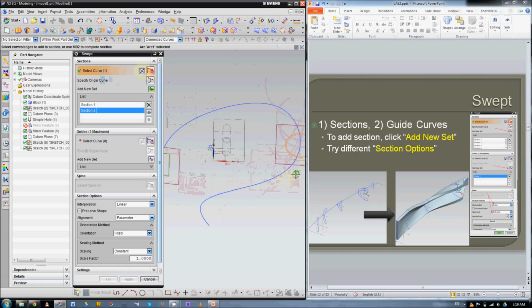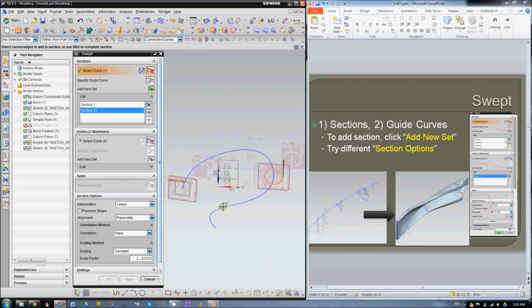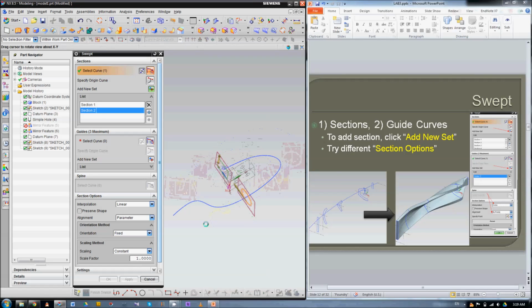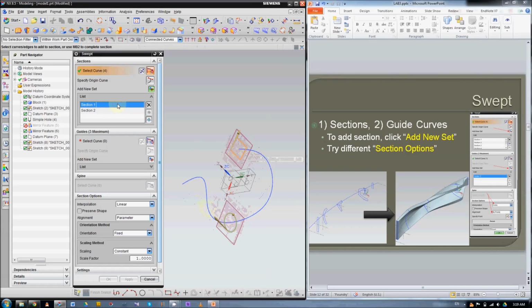But if you want the sweep to be nice and match each other, first the direction of the cross section should be the same. If you look here, this is counterclockwise, and that direction is actually clockwise. And remember, this thing sweeps along the path, so these 2 directions should match each other. So I want to reverse the direction of the first section.